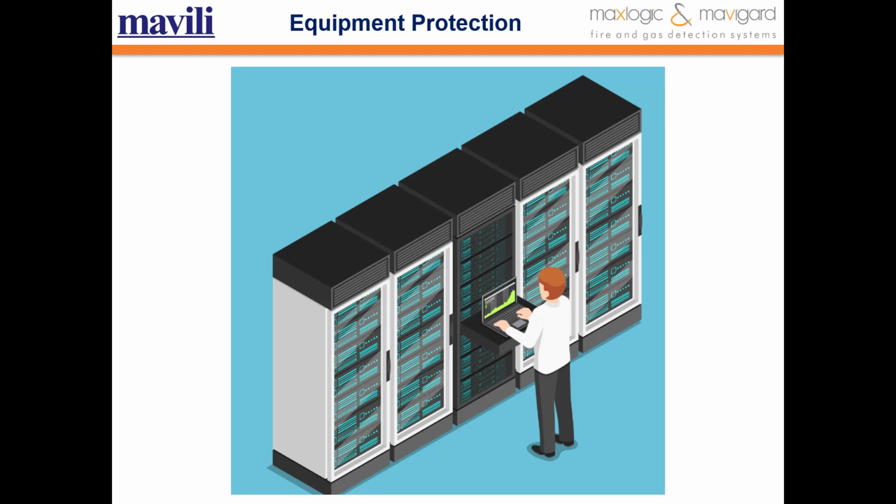Gaps, including underfloor and overhead gaps, should be protected with detectors only in the following cases. First, if the fire is likely to cause the widespread of fire or smoke outside the relevant space before it is detected by detectors outside the space. Second, if a fire in the space is likely to damage the emergency system cables before the fire is detected.